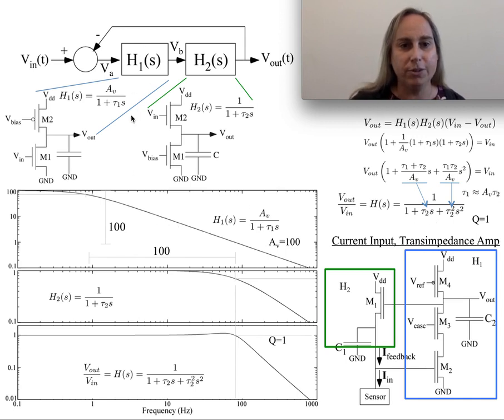Well, if you look at H1, which is a high gain, maybe it's a gain of 100, and then it falls off as a first order response, right? Integrator response at this stage. Maybe you'd think 20 dB per decade response. And you can definitely see that there's a gain of 100 there. Well, if I plot this and I plot H2 as having now a tau that's 100 out for a gain of 1, you would look at this and say, oh, okay, I can kind of see these two responses. They are quite separated apart.